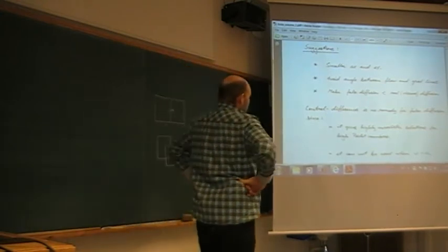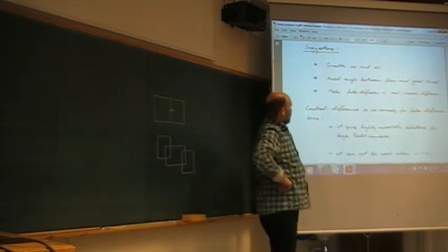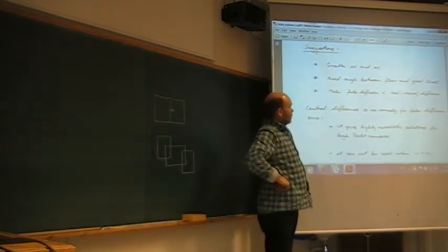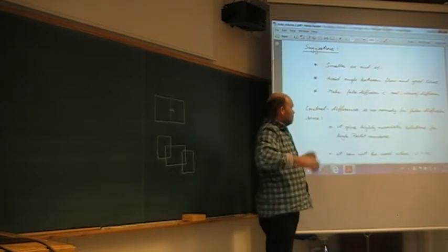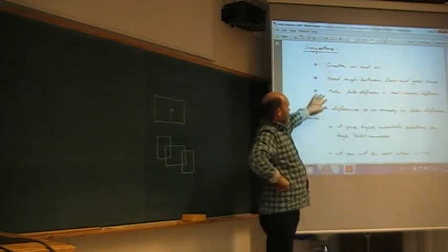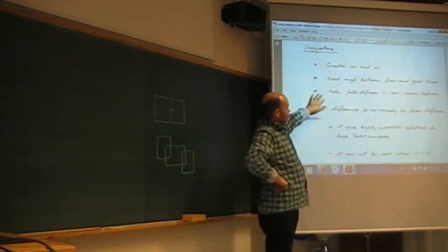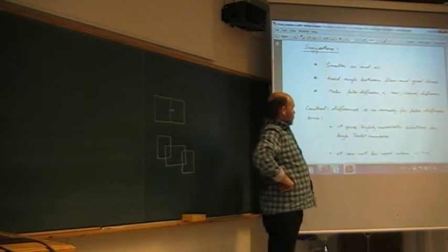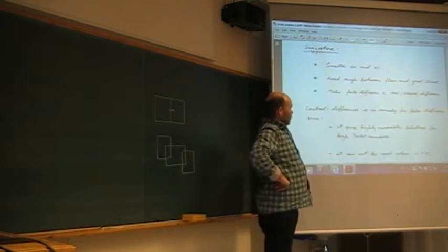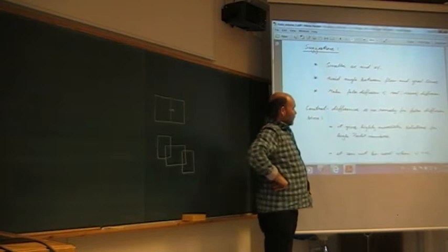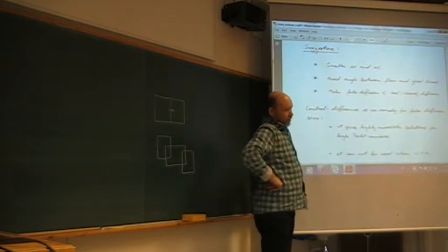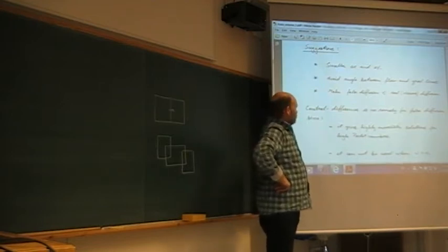Yes, that's an option, depending on the geometry, of course. It can be tricky if you have transient flows. And of course, make the false diffusion smaller than the real viscous diffusion. It's sort of essential, or else you are simulating the wrong Reynolds number.